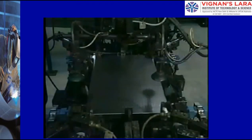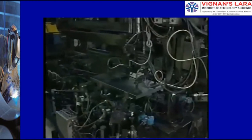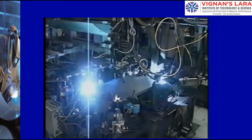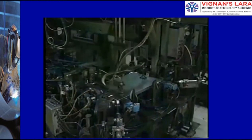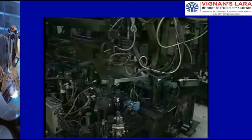Workpieces can be joined with or without filler metal. Plasma arc welding can be used to join most ferrous and non-ferrous metals, including extremely thin materials such as foils. Plasma arc welding equipment cost is high, however, so the process is often limited in its application.